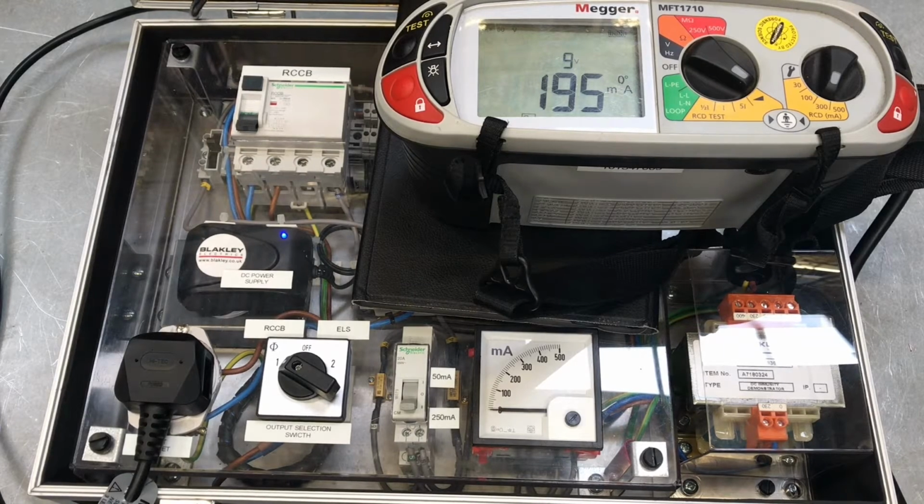So naturally, what do we do? You'll go out, go into the van, sit and scratch your head and go, have I done something wrong? And then you'll look up and you'll go, solar panels on the roof. Oh, that's what that box was next to the mains. There's an inverter there. Well, let's go in and have a quick look. Open up the box of the inverter, maybe there are burnt out DC terminals coming in. There may be damage where the DC enters the box because it's not been protected against mechanical damage.